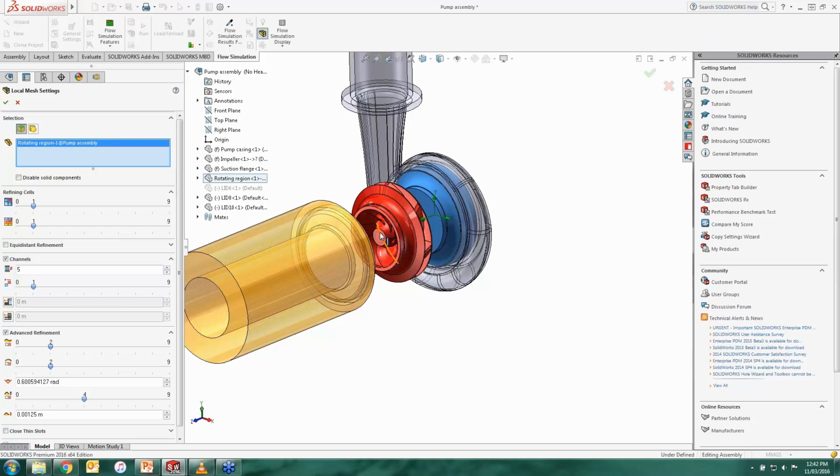So there are so many adjustments I can do by refining the cells in fluid, and refining the cells on partial cells, which means exactly the interface of fluid and solids. What we do for narrow channels, what sort of refinement level, and the other factors, as you can see here, small solid feature refinement level, or even curvature, let's say approximately level, making this more to the 9 level or getting back to the 0 level simply means more fine or more coarse mesh we're generating.